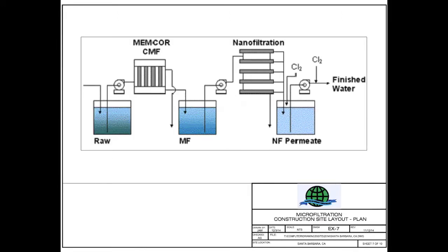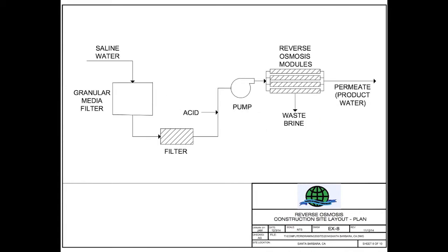The microfiltration system precedes the reverse osmosis process because it, unlike the reverse osmosis process, can be cleaned through backwashing. This protects the reverse osmosis process from fouling and gives its membranes a longer lifespan. Because we have incorporated a microfiltration process before our reverse osmosis process, it is possible for us to increase our water yield from 50% to almost 80%.